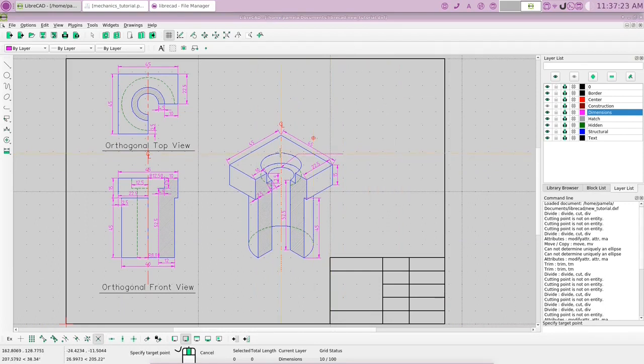Let's click on there. Let's take the intersection snap off. Let's snap here. Let's put the horizontal restraint on, and let's snap here. There you go. We got a couple of leaders there.